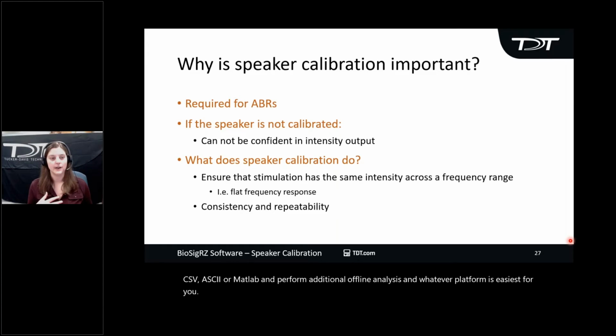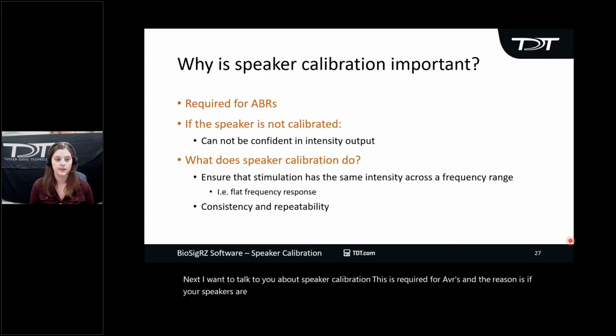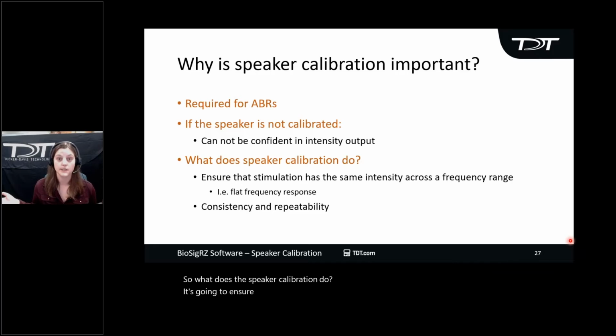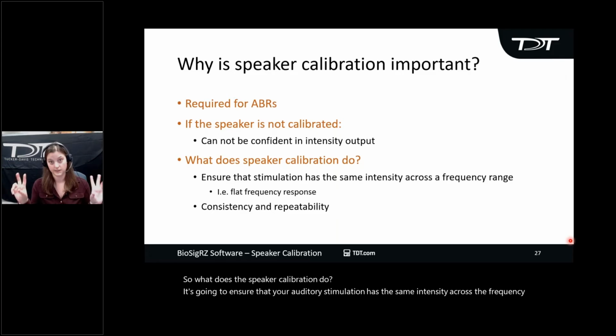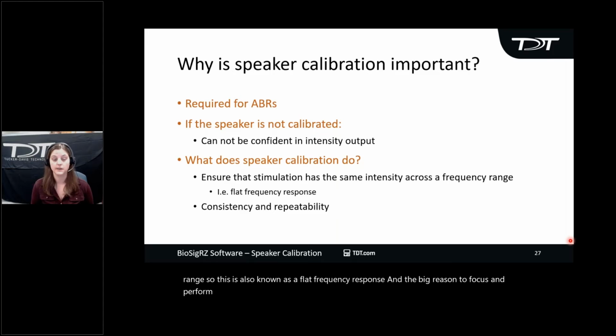Next, I want to talk to you about speaker calibration. This is required for ABRs, and the reason is if your speakers are not calibrated, you cannot be confident in the intensity the speaker is delivering. So what does a speaker calibration do? It's going to ensure that your auditory stimulation has the same intensity across a frequency range. So this is also known as a flat frequency response. And the big reason to focus and perform speaker calibration is it's going to give you consistency and repeatability during your ABR experiments.